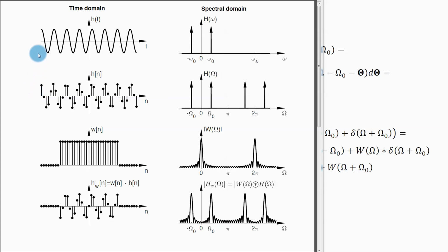If I sample a sine, which is an infinitely long signal, I will get an infinitely long sequence of numbers, and that you are not going to process in MATLAB. So in real-world recording, in addition to sampling a signal, I need to cut my recording and sample only a finite number of samples. I need to cut this signal to a finite length. But if I cut my signal to a finite length, will it not change the spectrum? Well, it will, and not for the better.